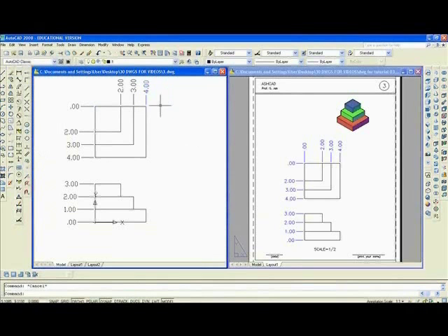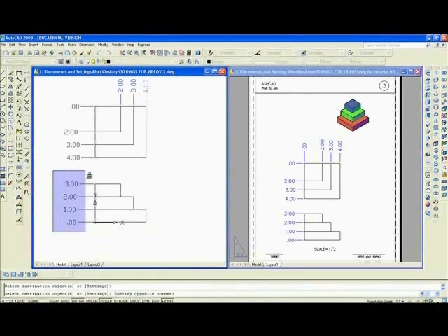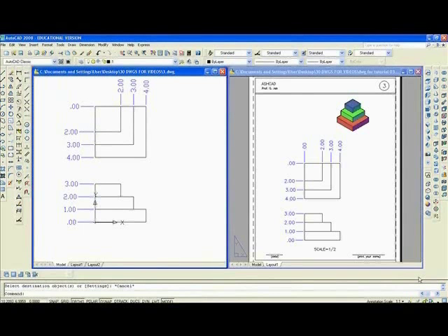Hit Escape. It did. And I can use Match Properties to select it, and then with the paintbrush I can do all of these. Well, that won't work. I can type C, enter for crossing, and then I can do that. So all the dimensions are now on the layer Dim. Hit the escape bar. And so the top view and the front view of these objects along with dimensions are complete, and I can proceed to make the solid model.